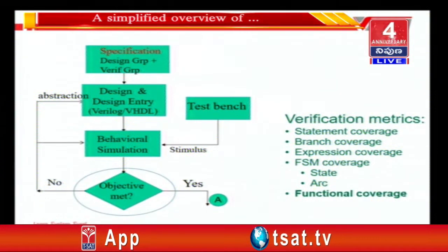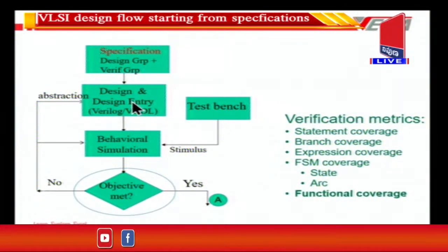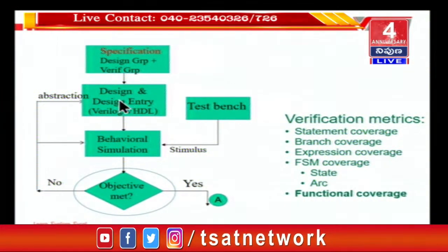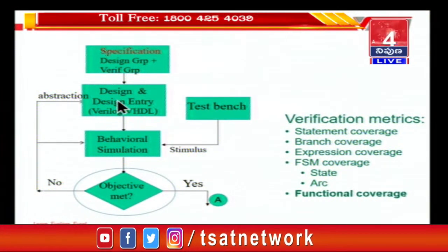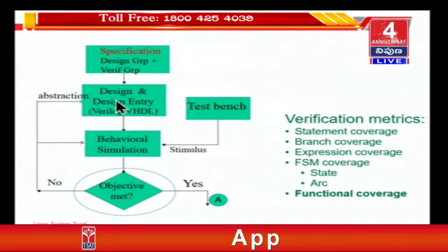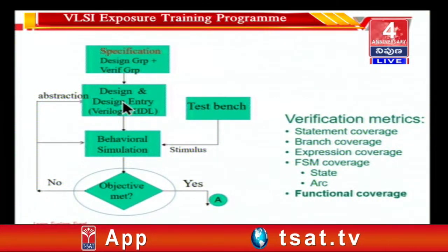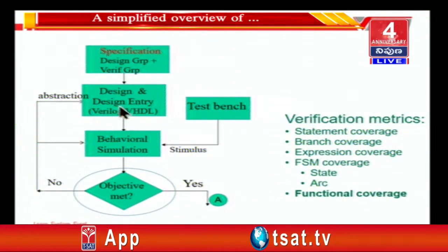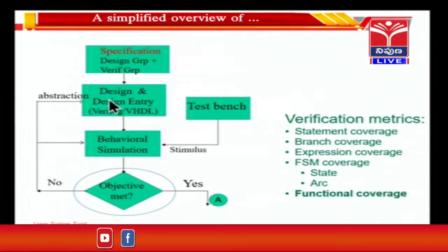Verilog can be written at various levels. Let me mention here, as a small digression, that Verilog can be written at the RTL level, many behavioral RTL level. It can be written at the gate level. It can be written at the switch level also. There is one more intermediate level called the data flow level.